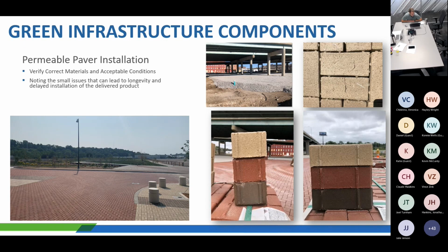This is a situation where the RPR noticed that the particular tan pavers were coming out with hairline fractures in them. He brought this to immediate attention. They were able to do some QA/QC back at the plant and send the correct pavers. It obviously didn't have severe cracking in them.